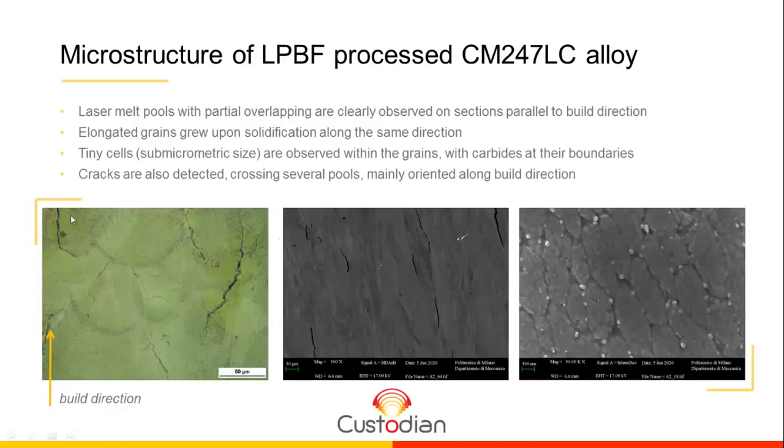Also, you might have noticed, we are dealing with some cracks, even after parameter optimization with a standard laser powder bed fusion process. We cannot avoid having them. They run across the melt pool tracks, usually crossing several melt pools.